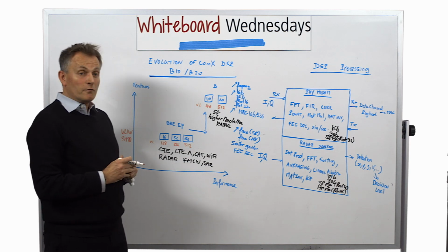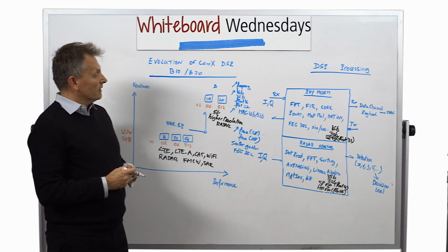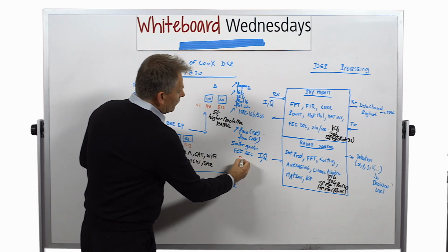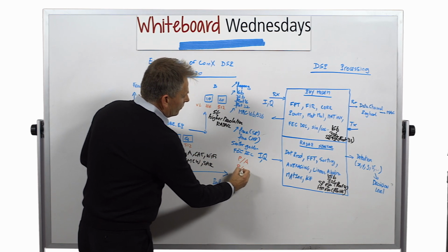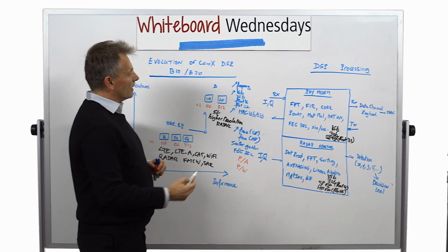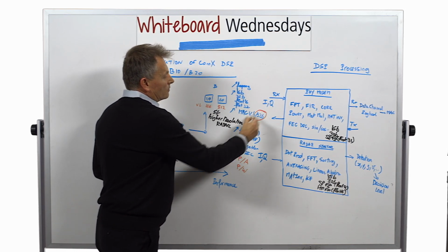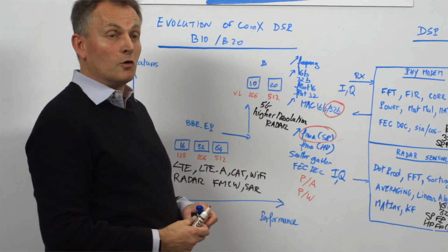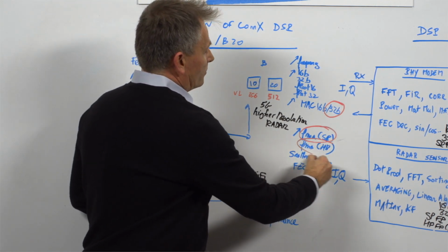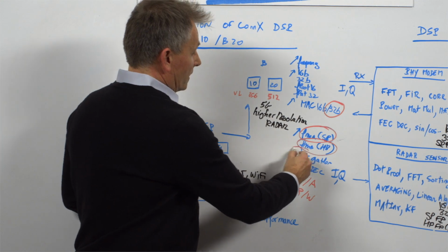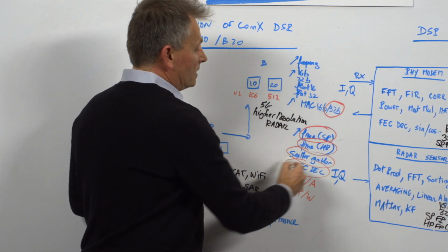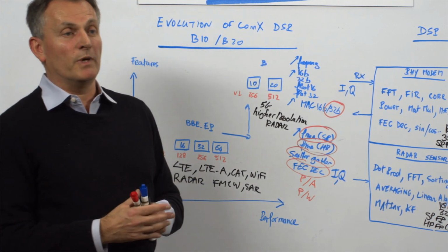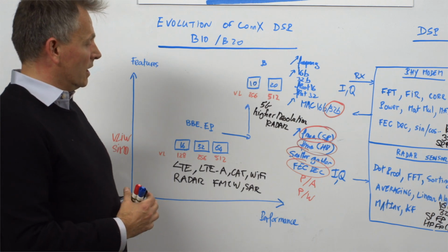Now, most of those features are also optional in order to be able to provide the right trade-off for performance over area, but also performance per watt. And so some of the options that you have available are the 32-bit options, or also being able to select or not the single precision floating point, or the half precision floating point, or the scatter gather, or eventually the FEC decoder accelerations. So those are various options that are available to make the best trade-off for the system application.